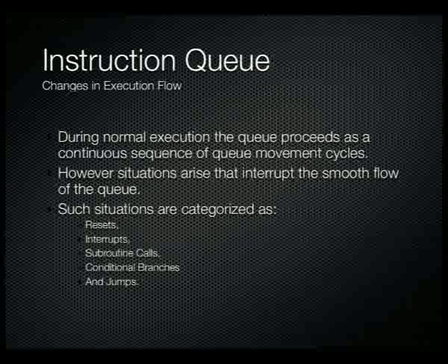So anything that changes our processor from working in a sequential manner will effectively stuff up our instruction queue. The instruction queue works very well as long as the queue is kept full. The second you change program flow, the queue has to be flushed and refilled, and there's a slight delay associated with refilling that queue. So the more sequential you can make your code, the faster it's going to run. But there are downsides to making code very sequential: it's not very modular, and it's very, very big.